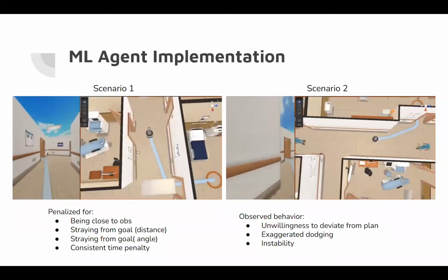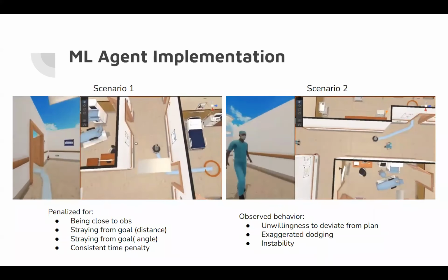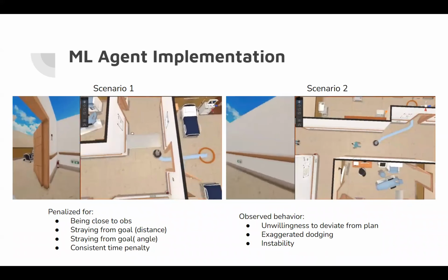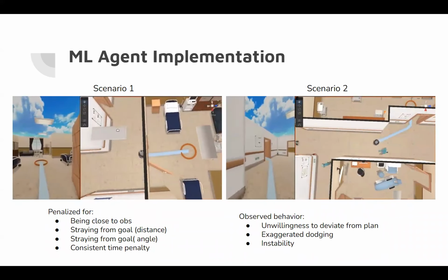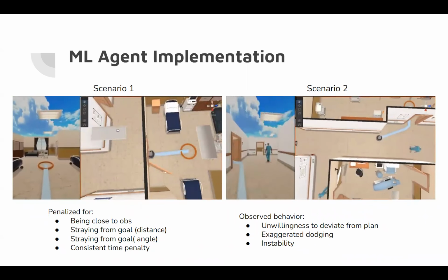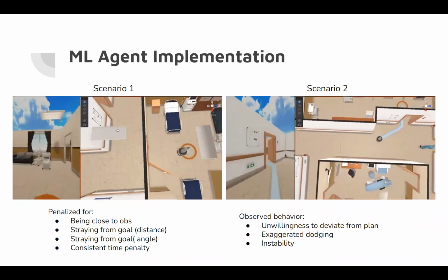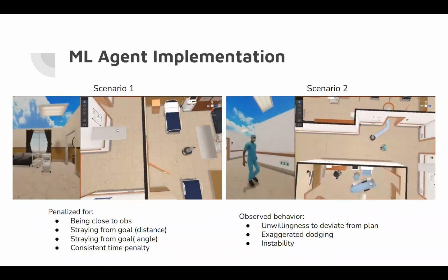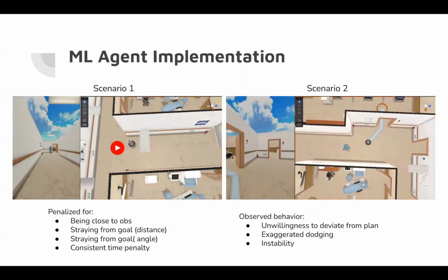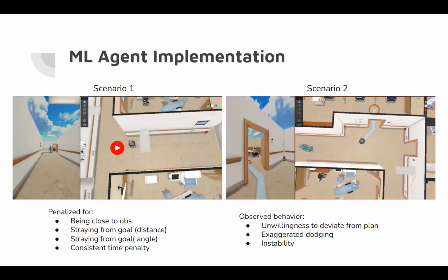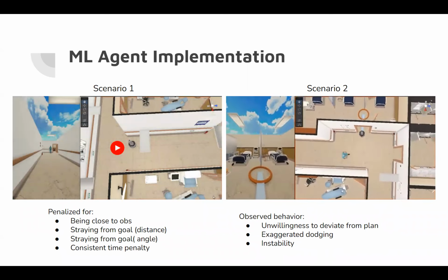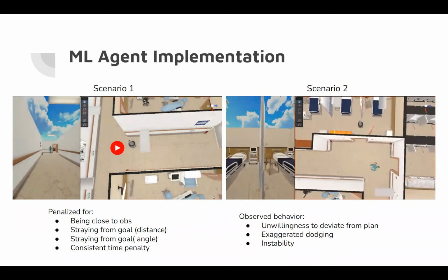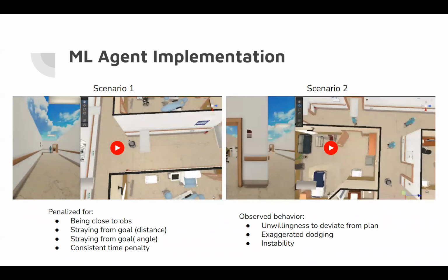From my observations, the robot navigates quite aggressively and exploits the fact that the human will avoid it. I also noticed significant jerking in the motion, and this can be undesirable if the robot is carrying medical supplies. I added a negative reward for changes in angular heading, and this improved performance, but ultimately to provide near perfect results, the ML strategy will require a lot of training and fine-tuning of the reward functions and the hyperparameters used in creating the model.